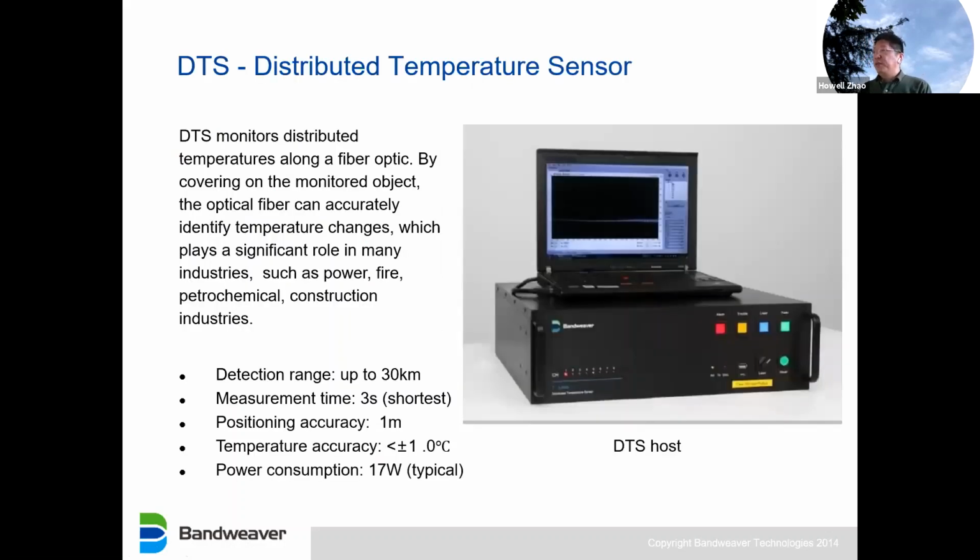Yeah, so finally, it looks like this. The laptop PC is not necessary. The box can work standalone. In the black box, we have laser, APD, optical filters, and other optical components to provide the light source, couple the fiber, get the backscattering, differentiate the wavelengths, and put the light into the photon detector.